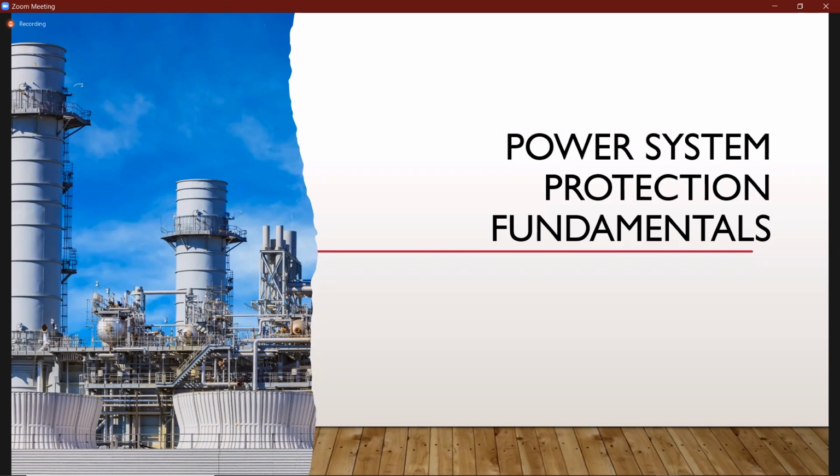And the first objective regarding the data required, part of the reason I needed you to focus just on that particular line is that what you would have recognized from early on, when you put the zero sequence and the negative sequence values to zero and ran that three-phase fault, you still got the same value, which is saying to you that the symmetrical fault uses only positive sequence impedances as part of the calculation.